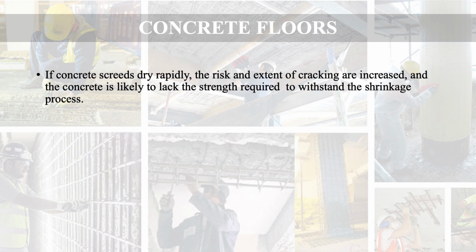If concrete screeds dry rapidly, the risk and extent of cracking are increased, and the concrete is likely to lack the strength required to withstand the shrinkage process. So that way, the drying should not be rapid.